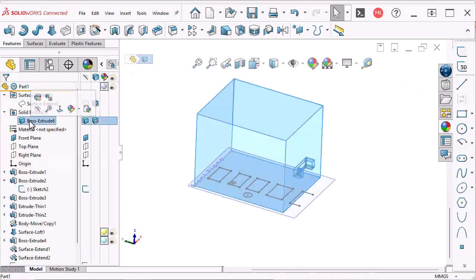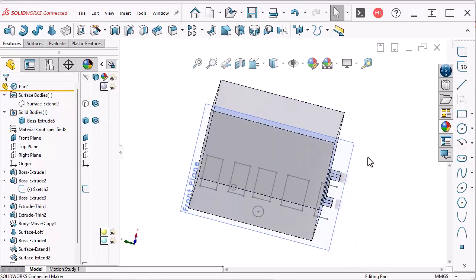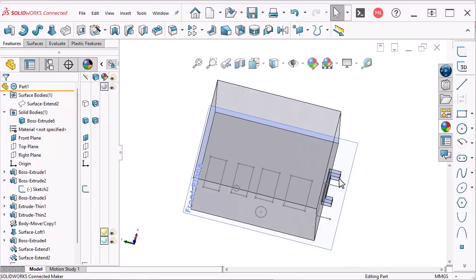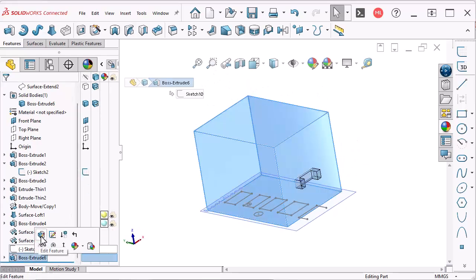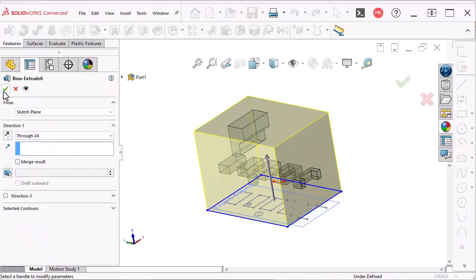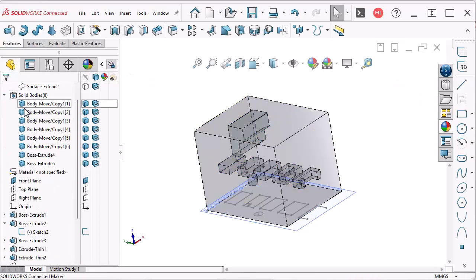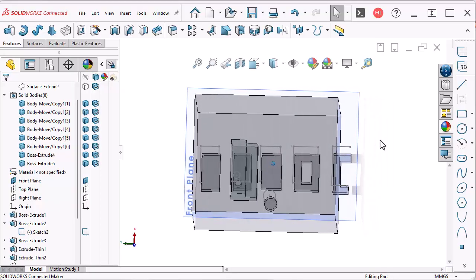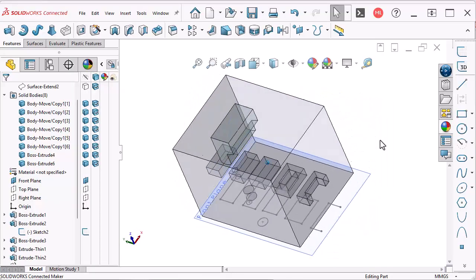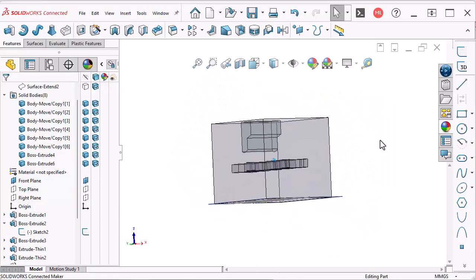It takes all of the solid bodies and consumes them or joins them into that solid feature. We go back again, we turn that option off, then what happens is all of these solid bodies remain as separate solid bodies. They're just taking up the same space as the new solid body that's bigger than everything else.